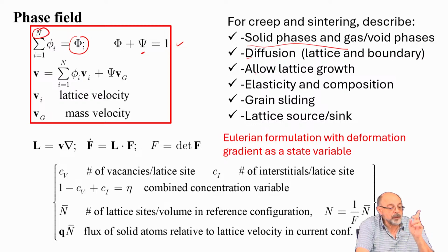Phases are not conserved here. But the driving forces for that growth will depend not only on interface energy, but also on elasticity, that is, on stresses, and composition, because composition creates its own eigenstress.